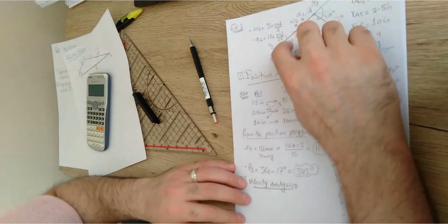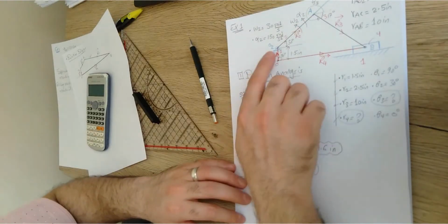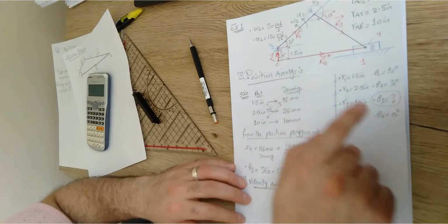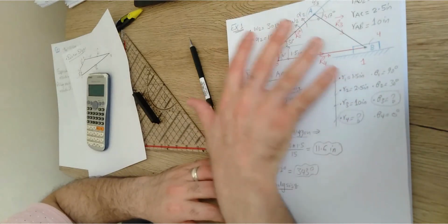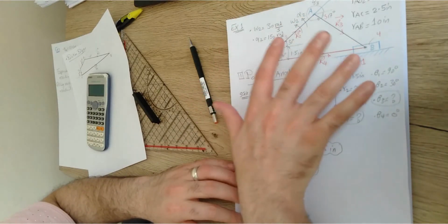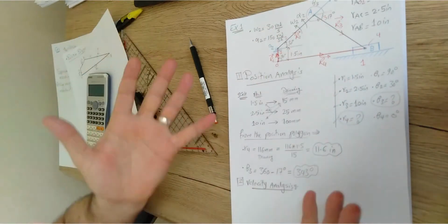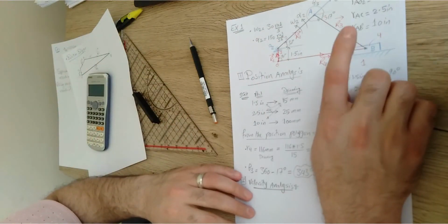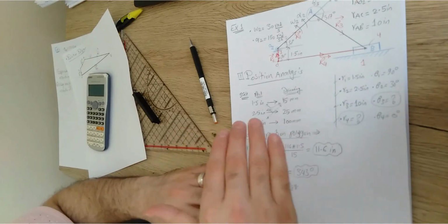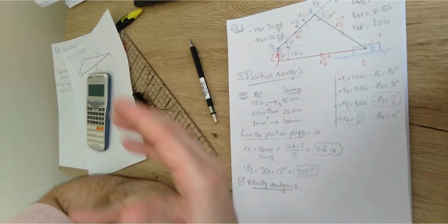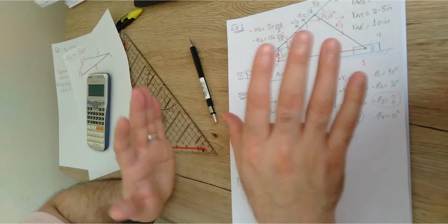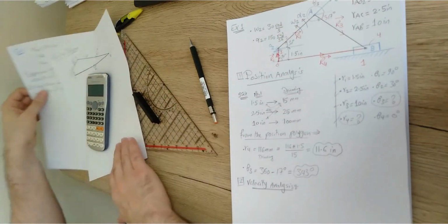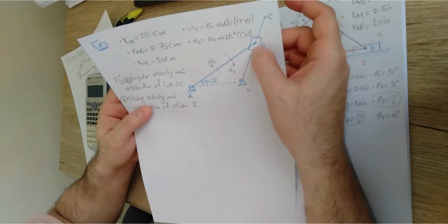The first one is that you have a link that rotates about a fixed point, like the link O2A. The second is a link that does general motion, with a fixed length like AB, and this link has no fixed point. The third case is that you have a slider that moves on the ground, either horizontal, vertical, or even over an inclined surface, but anyway just a slider that moves. The fourth case, which is in the second example, is when you have a slider on a link.